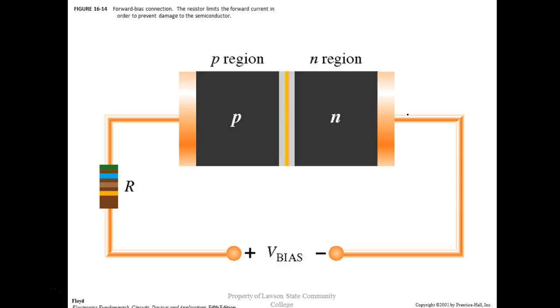Well, used to, but now what they do is they have a constant current source. On digital meters, they put a constant current source. So what happens on your digital meter, it outputs a current, like 1 milliamp. And what it does is that when you hook it up, it steps the voltage up until 1 milliamp flows. Then when 1 milliamp flows, it says, okay, and then it converts that, the voltage would be exactly the same, and then they put the decimal point in the right place and they put ohms on the outside.